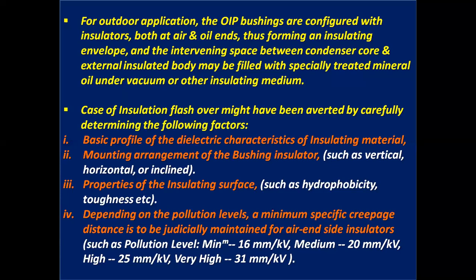Number 3, properties of the insulating surface, such as hydrophobicity or toughness. Number 4, depending on the pollution levels, that is environmental pollution, a minimum specific creepage distance is to be judiciously maintained for air side insulators.